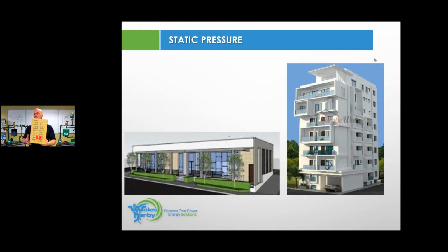So the myth is out there that the height of the building matters. This is that 5-story building on the right-hand side. If my boiler room is right here, and Jim said last week about total equivalent length, we would measure the heat circuit up to the top of the building, over, down, and back to the boiler. We would take that number, multiply it by 1.5, then by 0.04. That would tell us the head loss of that heat circuit. So the confusion comes in: this is a 5-story building, that heat circuit, let's call it 300 feet. If I take this and make it a 1-story building, and my boiler room is still here, that pipe distance is still the same, that circulator size does not change.